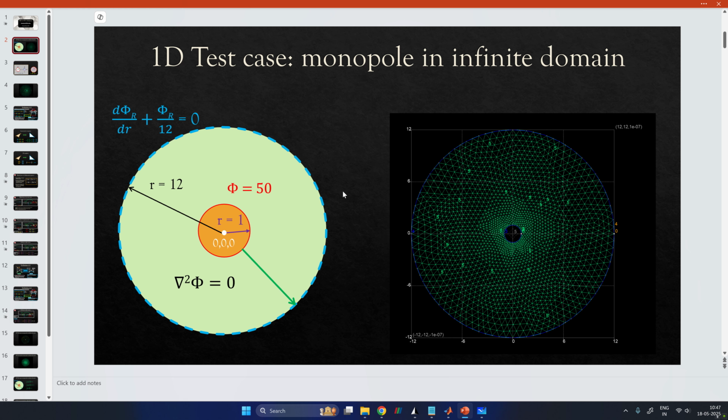So the solution will be different, but this will allow us to understand a lot of 2D-related finite element stuff. The basic stuff which we want to learn: developing a 2D mesh on Gmsh, what triangles are, what quads are, how you handle the derivatives, what the Jacobian of transformation is, and what the mesh quality is, and what parameters we can use to judge our mesh quality. So really we can understand all of these by this simple example, and we'll use the same kind of Robin condition, though